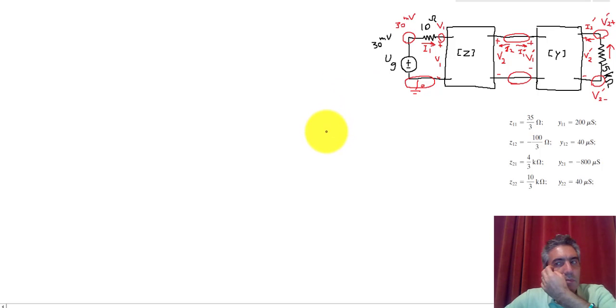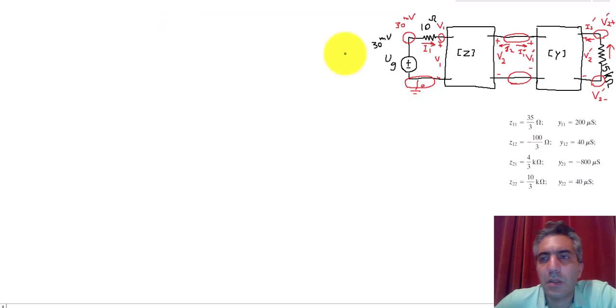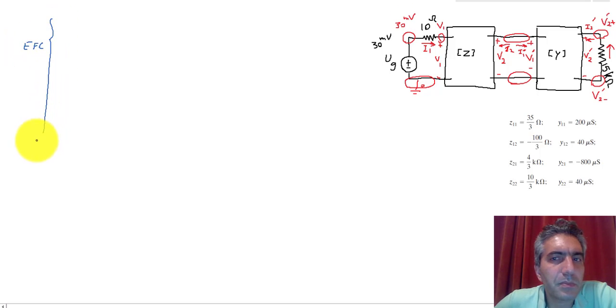Okay, now I'm going to start writing the equations. Obviously there are no KCLs, so we're going to directly move on to writing equations for components. Start with the 10 ohm. I1 is equal to 30 millivolt. So if I write everything in millivolt and resistors in ohm, then all the currents are going to be in milliamp. So 30 minus V1 divided by 10.